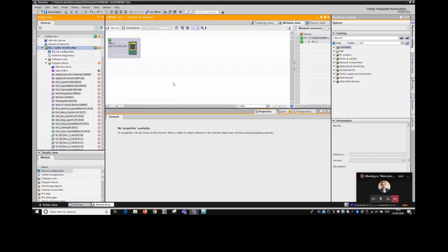You then put it in a box, send it to the customer's site. The customer will then just take it out of the box, power it up, and because the connection is from the remote device into the server, it connects that way. Once that connection is made, you can finalize and complete your connection remotely using the Sinema software. So that does enable you to simplify if you've got customers out in the field that you can't get to site, but you want to gain remote access.